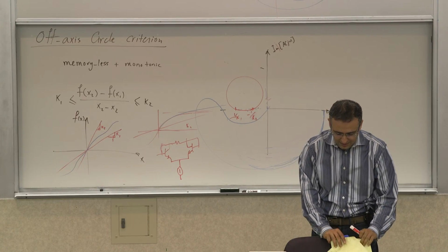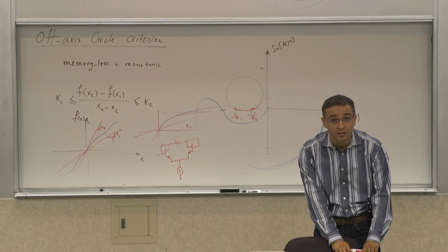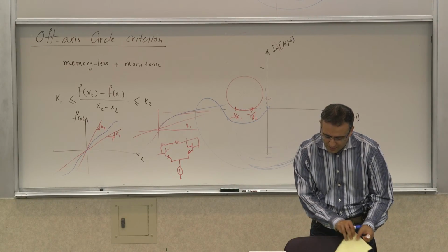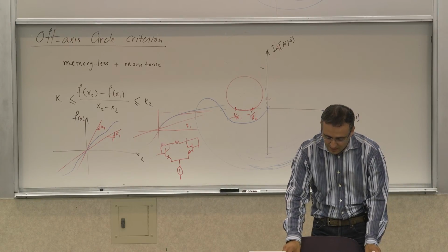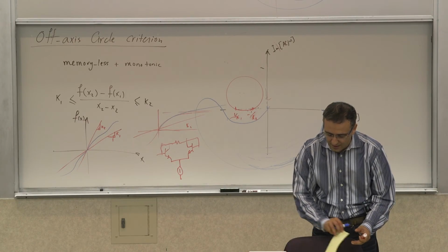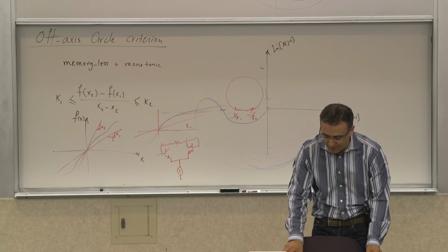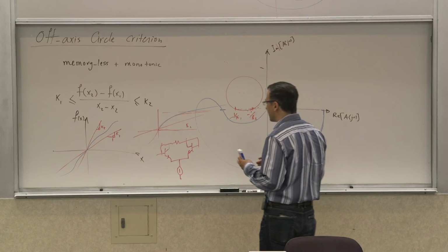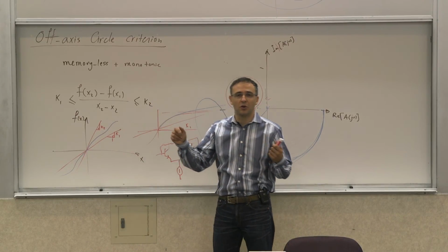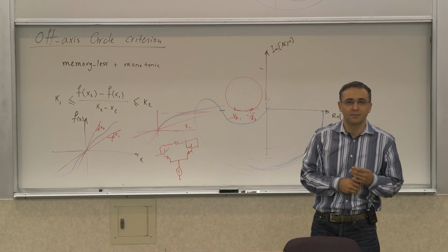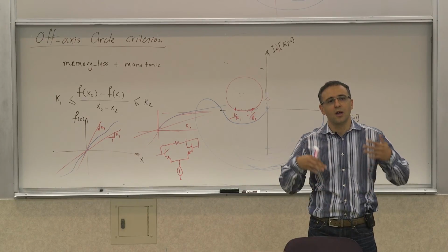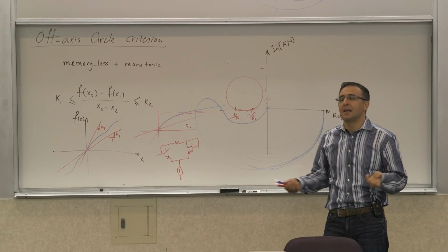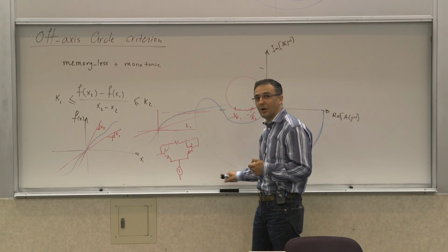Okay, so that's a good question. Any other questions? No other questions? Okay. So now there's one more thing I want to talk about in this context. If you think about these questions of oscillation, we talked about the Barkhausen criterion, and we saw that in the light of the Aizerman and Kalman conjectures not being true. You see that a lot of those things in nonlinear systems are not necessarily true. So you don't see guaranteed oscillation, or you won't know whether you have oscillation or not.